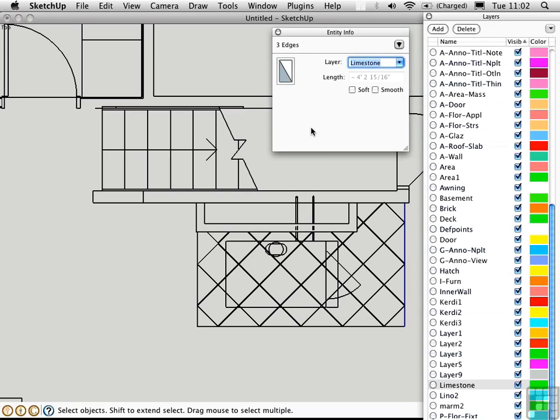That's another good question. This is the kind of work that you end up doing when you import drawings from AutoCAD or another CAD program. There's really a lot of cleanup to be done. And some of this can be done in the CAD program where you created the information, or you can take on that task here in SketchUp. There are really 2 different schools of thought when it comes to CAD cleanup. In School A, which I'll call Perfection, all the lines have to touch and close, little extraneous lines need to be deleted, everything needs to be on the right layer, and it's really quite a tall order.